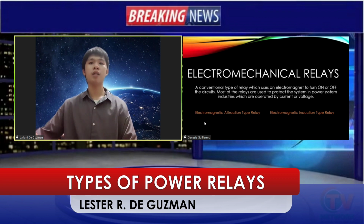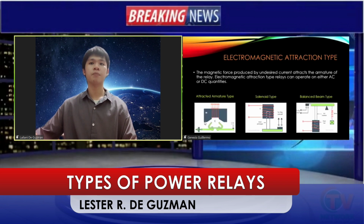Electromechanical relays, a conventional type of relay which uses an electromagnet to turn on or off the circuit. Most of the relays used to protect the system in power system industries are operated by current or voltage. They are classified into electromagnetic attraction type relay and electromagnetic induction type relay.